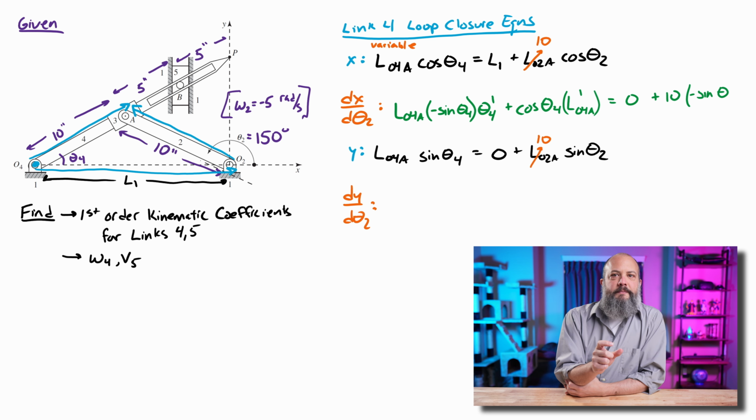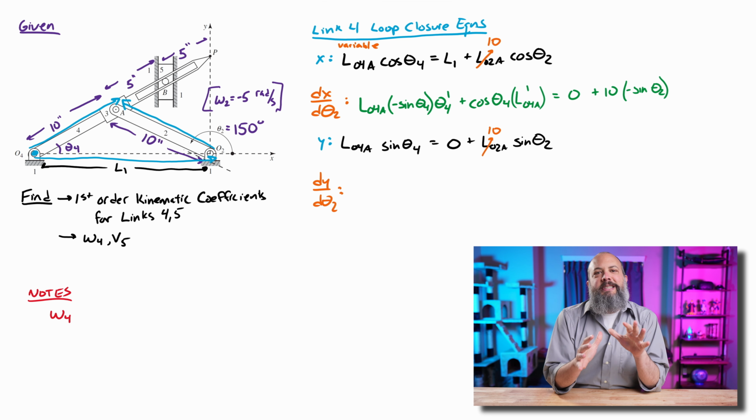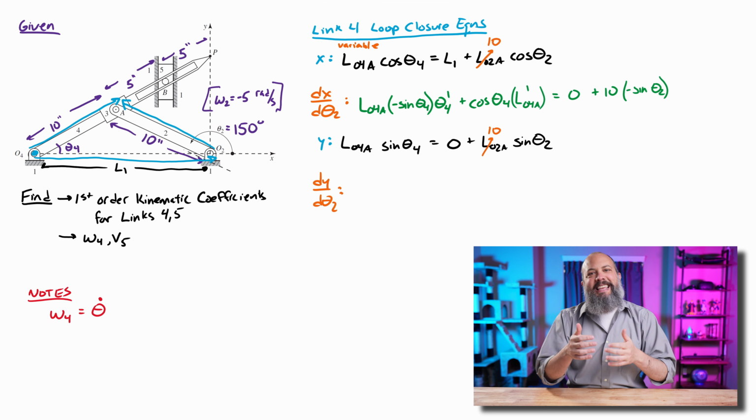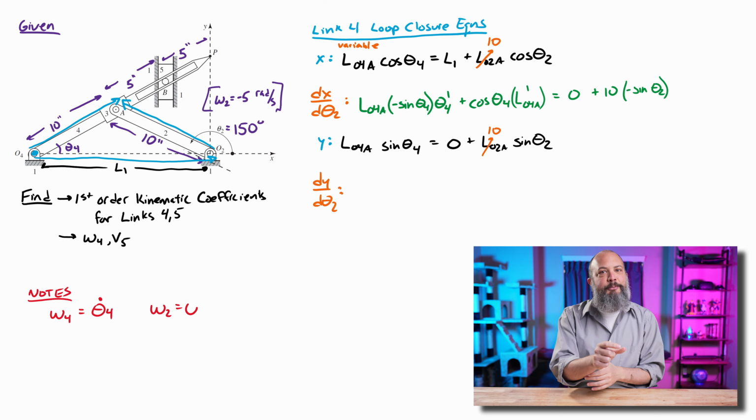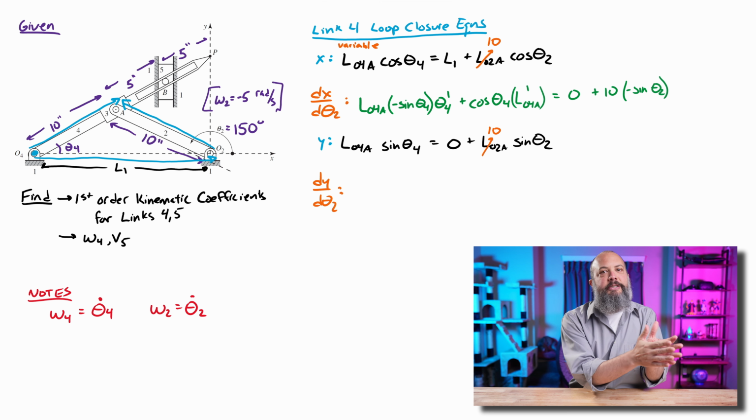All right, and now I want to take a real brief aside for a moment and talk about derivatives. So using the complex algebra method, you're probably used to taking a time derivative as the next step. And when you take, say, the time derivative of an angle that is changing, you get, because of the chain rule, an extra term kind of pops off to the side, like a theta dot term.